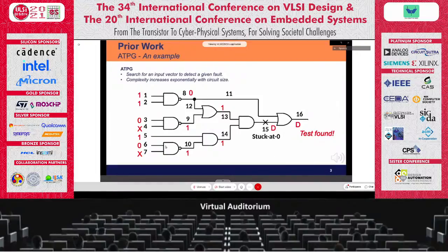For a circuit with I inputs, these I may include scan latches in case of scan-based circuits, ATPG may need to simulate 2 raised to the power of the number of primary inputs of the circuit vectors to find a test. Although ATPG algorithms typically find tests without simulating close to this many vectors, this upper bound still exists and is occasionally seen in modern circuits.